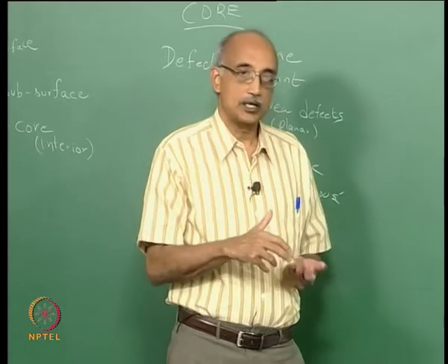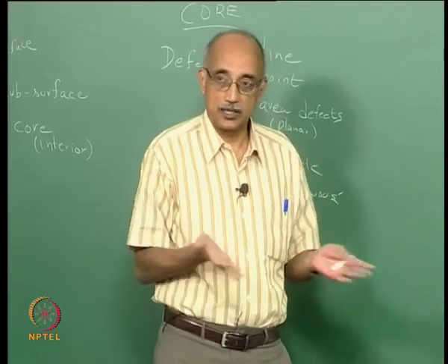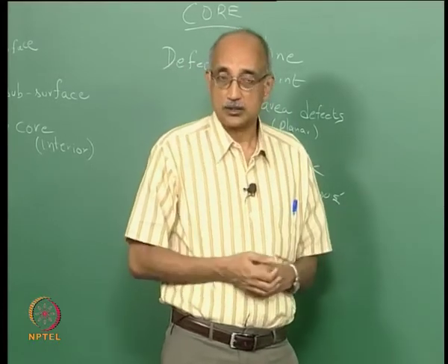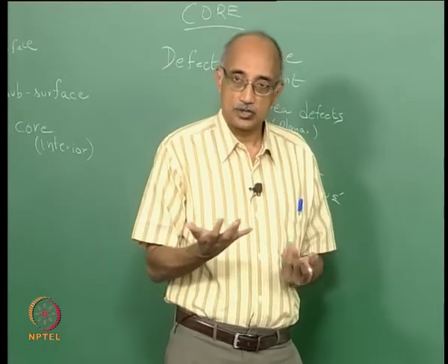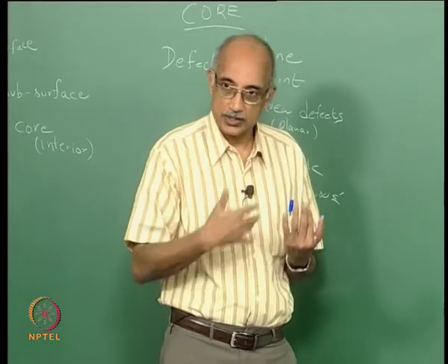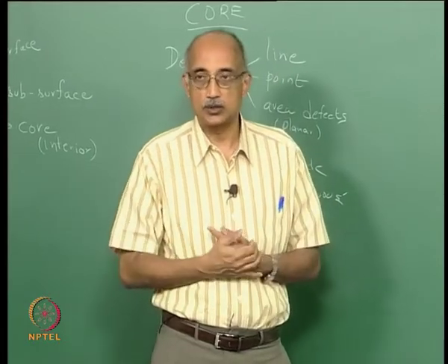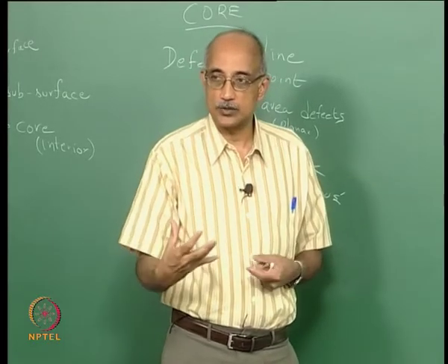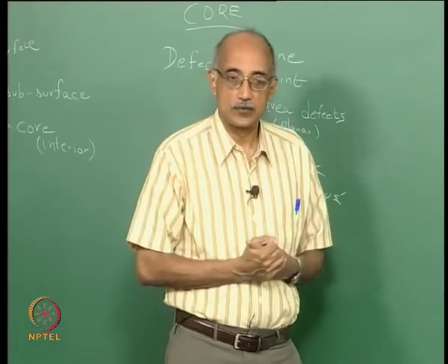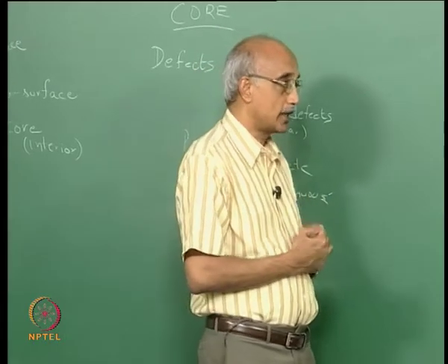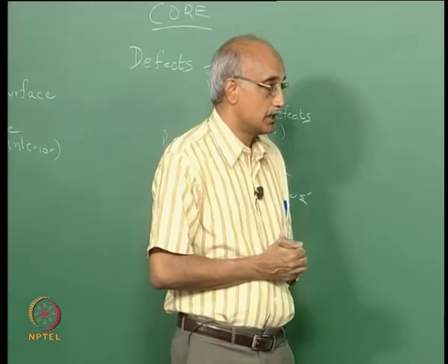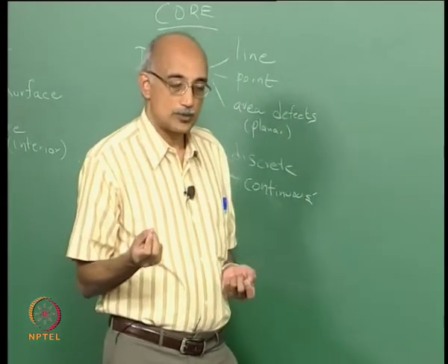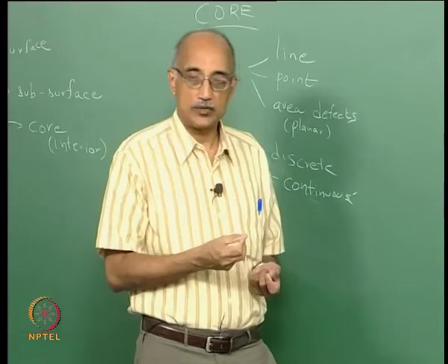And what I want to try and do is increase that surface area as much as possible. So I want a porous structure, I want the reactants and the products to be able to diffuse easily down to the subsurface region and then back out. So I am not interested in hermetically sealing the surface so that everything only happens on the surface. What I really care about again is the total catalytic area which promotes chemical reactions between the various reactants